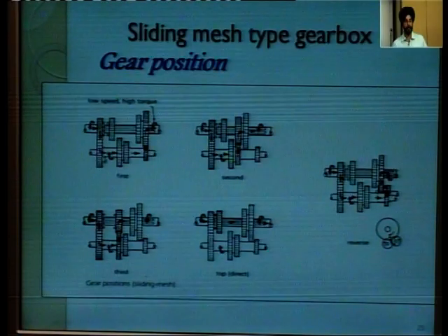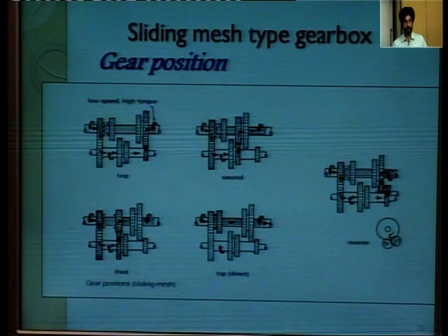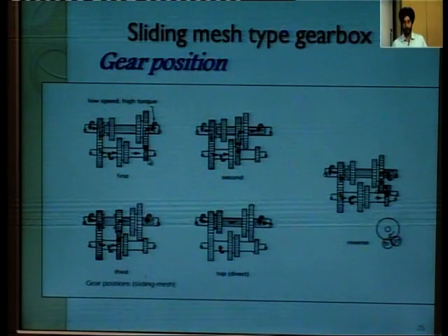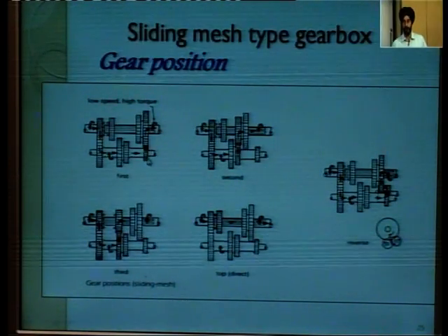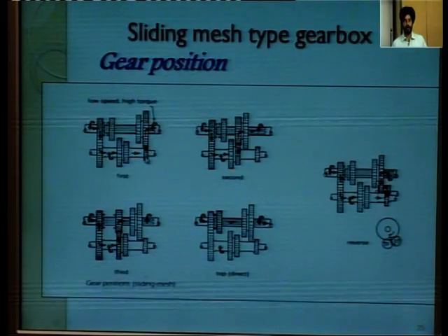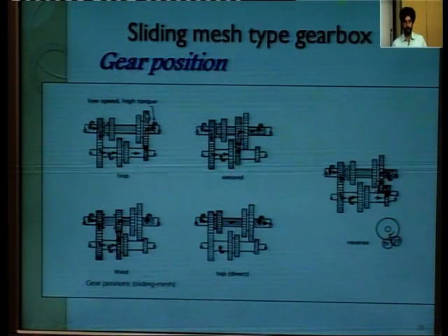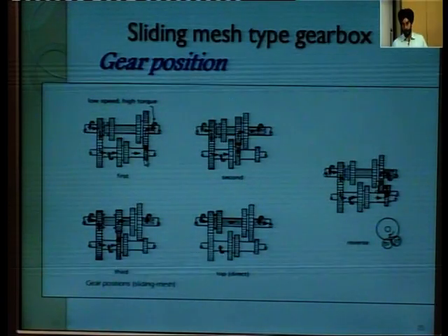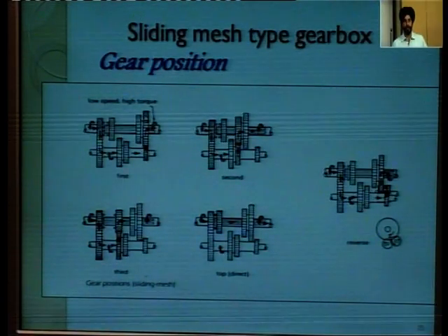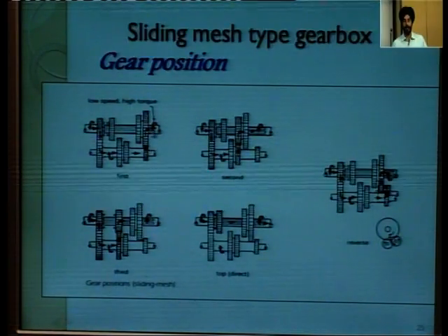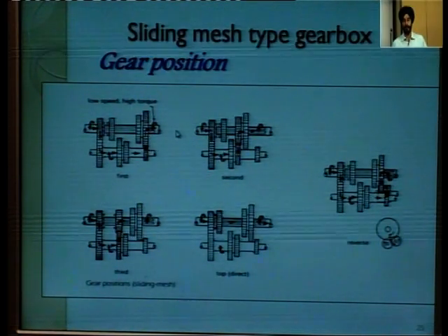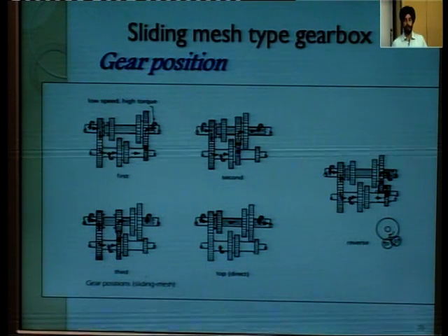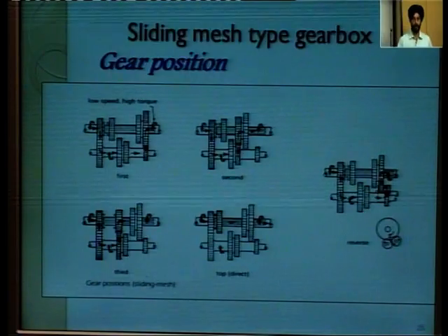The lay shaft gear is moving this shaft with the same RPM for all gears, and from this lower gear, the gear which has fewer teeth is matched with the gear with the larger number of teeth. This will transfer power to this bigger gear, and we get output in terms of reduced RPM and increased torque.